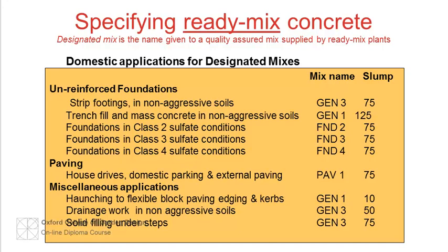Access difficulties for the delivery lorries may be overcome by pumping ready-mix concrete from the mixer lorry along 150 mm diameter pipes. Horizontal distances up to 25 meters and vertical distances over obstructions up to 10 meters high are possible even for moderate quantities.